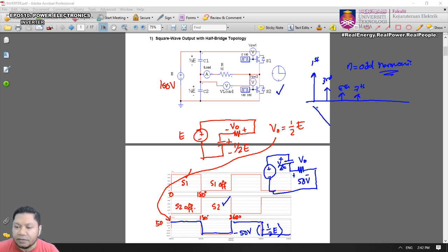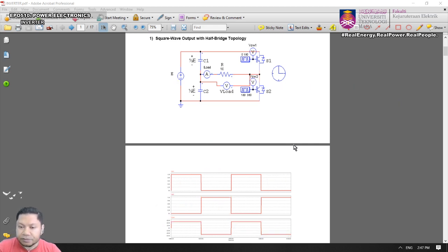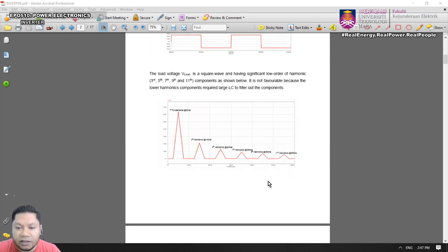And the amplitude for these harmonics, we're going to have Cn equals the magnitude of 4 IDC over n pi. So if n is 1 or 3, 5, you just replace that, then you can get the amplitude of this harmonic spectrum, right?